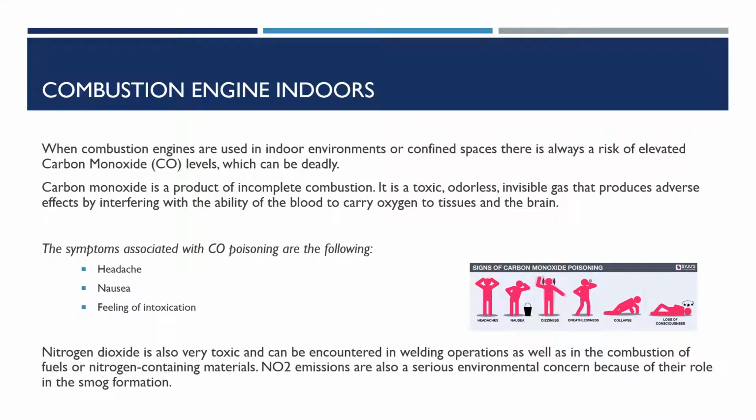Combustion engine indoors. When combustion engines are used in indoor environments or confined spaces, there is always a risk of elevated carbon monoxide levels, which can be deadly. Carbon monoxide is a product of incomplete combustion. It is a toxic, odorless, invisible gas that produces adverse effects by interfering with the ability of the blood to carry oxygen to tissues and the brain.